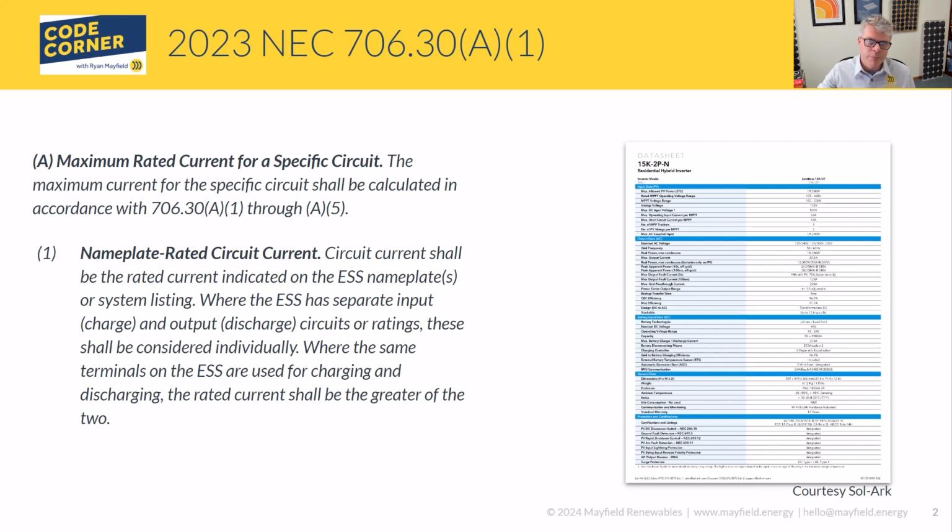But again, if you've been using Article 690, we're going to use this very similarly. The thing to take away from this is, just like in 690, this is going to define what our maximum current is. So this will tell us what the maximum value is on these different circuits. And from there, we're going to apply different safety factors or conditions of use, things like that. So you're going to be doing your derates on top of these values.